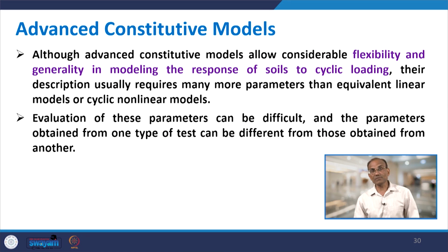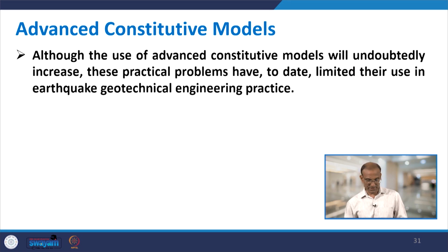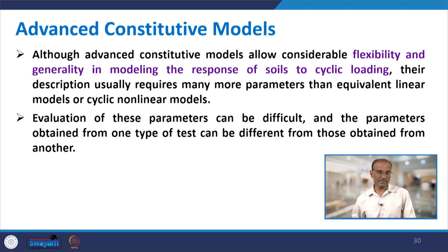Although advanced constitutive models allow considerable flexibility and generality in modeling the response of soil, their description usually requires many more parameters than equivalent linear models or cyclic nonlinear models. Evaluation of these parameters can be difficult, and the parameters obtained from one type of test can be different from those obtained from another. If you find the same parameter using one test, you will find a different answer if you conduct a different test.